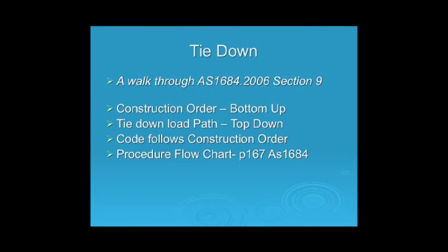Okay, so you're starting at section 9 at the back of 1684. Then bracing is section 8. And member sizing is basically everything that comes before that. So the first step is determine whether the fixings are nominal fixings or specific fixings. What you do to do that is a special chart we go to, and nominal fixings is quite simple.